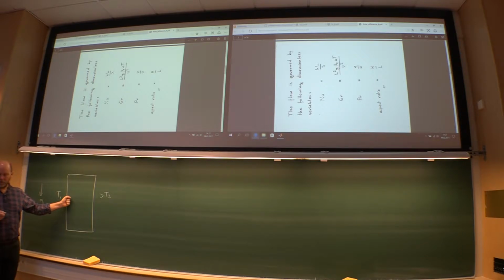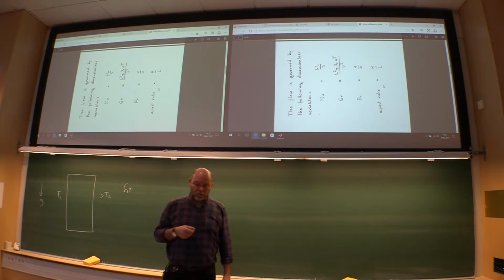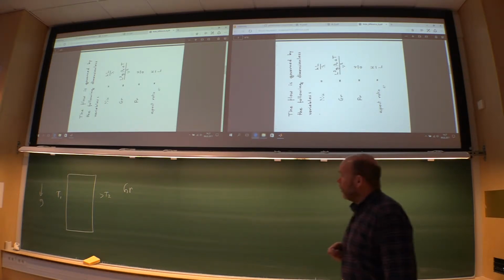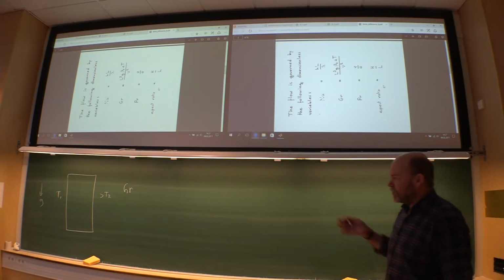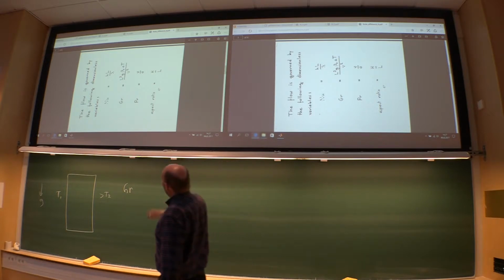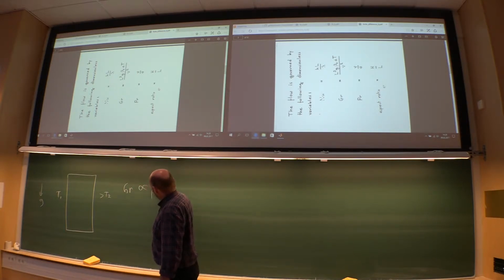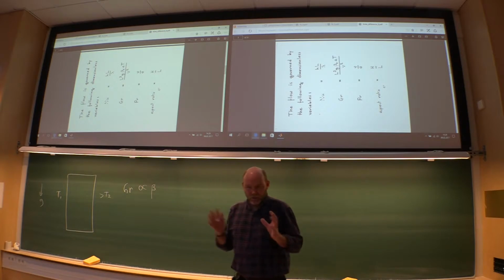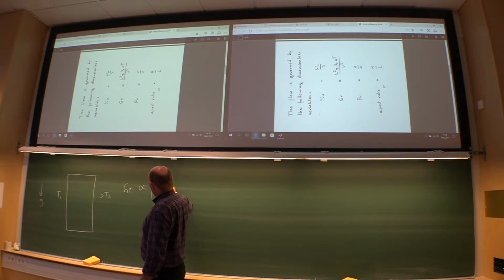It has a driving force upwards. Cold fluid then goes the other way around. And the driving force in the problem here is called a Grashof number. So that's one way to deal with the thermal expansion without actually doing the expansion. So it's still an incompressible flow. And as you see from this Grashof number, it is proportional to the beta parameter, that's the expansion coefficient for the density, multiplied with a temperature difference.